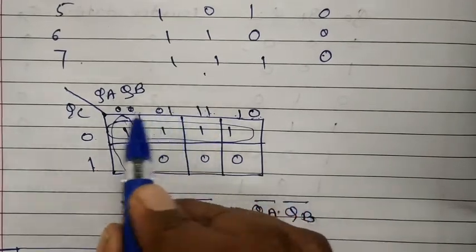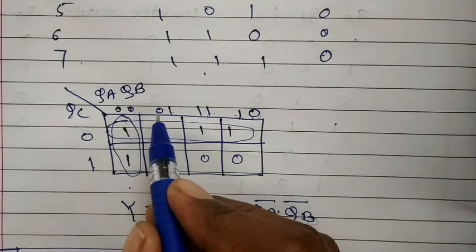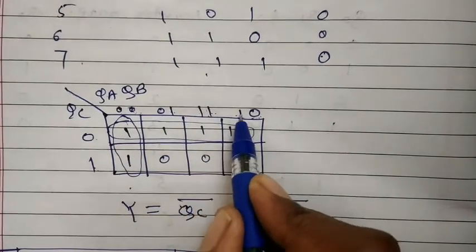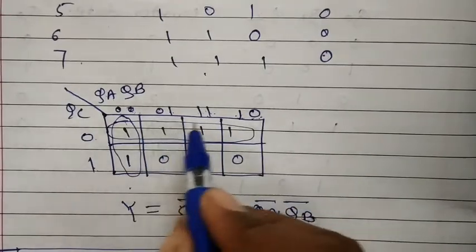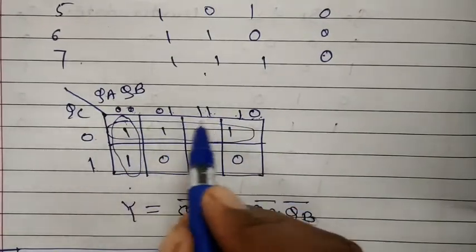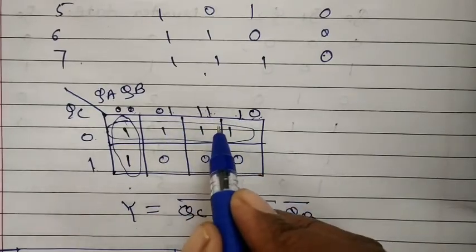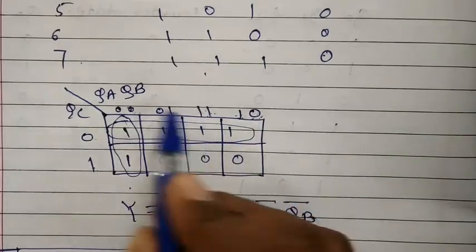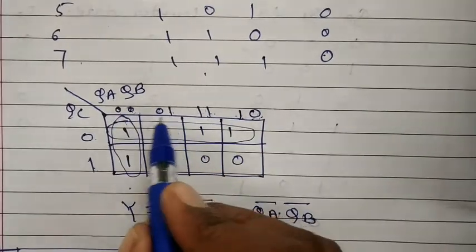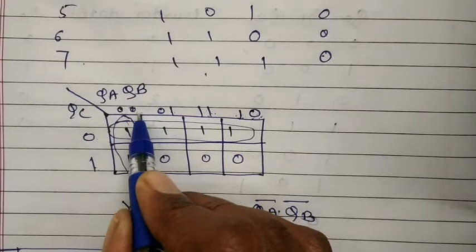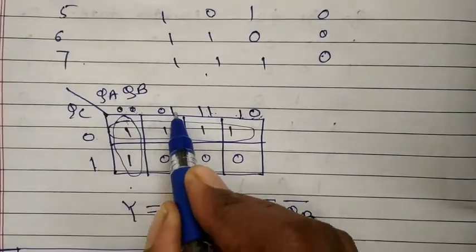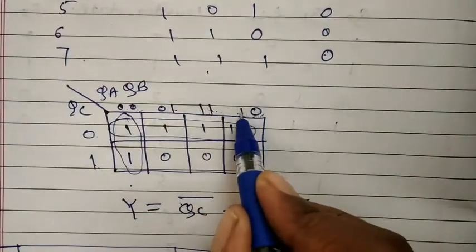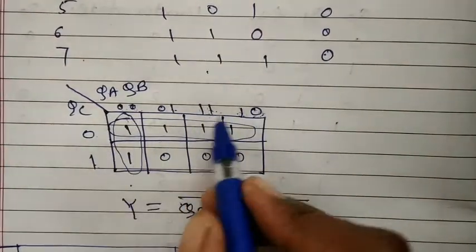And to keep 1 bit change in the numbers, I am taking 1, 1 first and then 1, 0 to avoid metastable condition or fluctuations in the circuit between 1 and 0. So I should get the 1 bit change in the digital form, which means 0, 0, then 0, 1. So there is 1 bit change. This is 0, 1. This is 1, 1. It's 1 bit change. And this is 1, 1. Next term is 1, 0. There is again 1 bit change in the digital number.